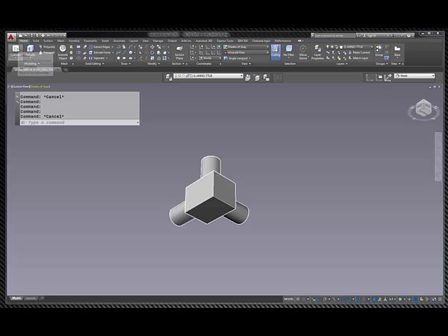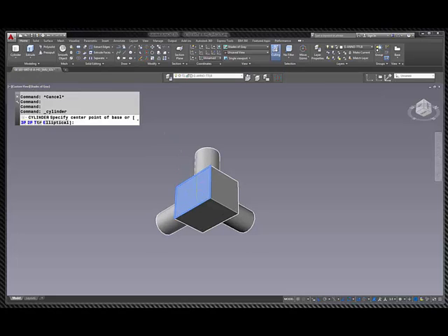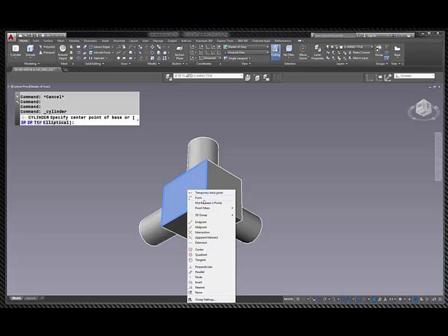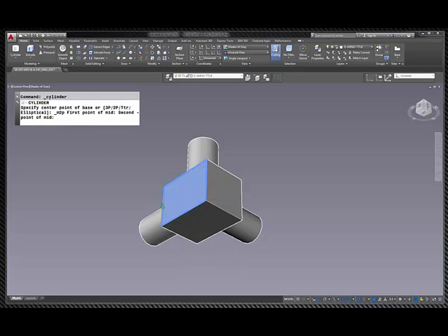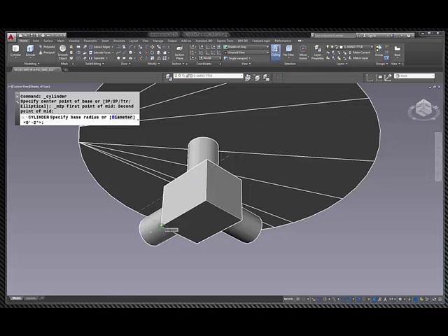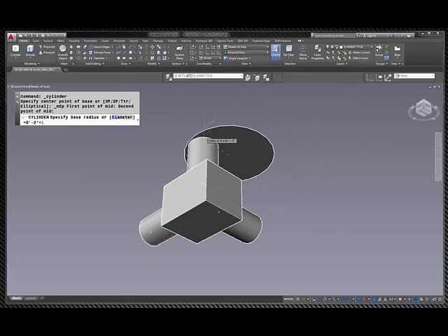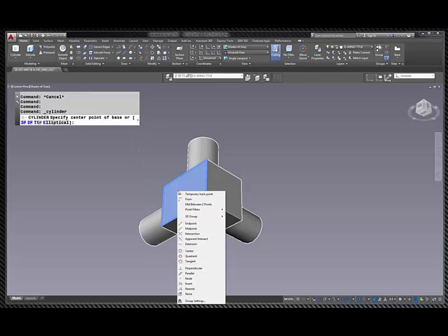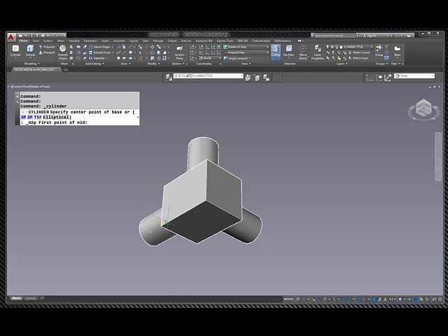Okay, I'm going to go to my cylinder again, and I'm going to come find the face. It turns color for me. I'm going to go shift right click, mid between 2 points. I'm going to go from there to there, and I'm going to go, oops. Okay, pick the face, shift between 2 points. Now see, I don't want to lose that color there. You have to be careful how you access this and whether you leave that face. 2 and 6. Okay.